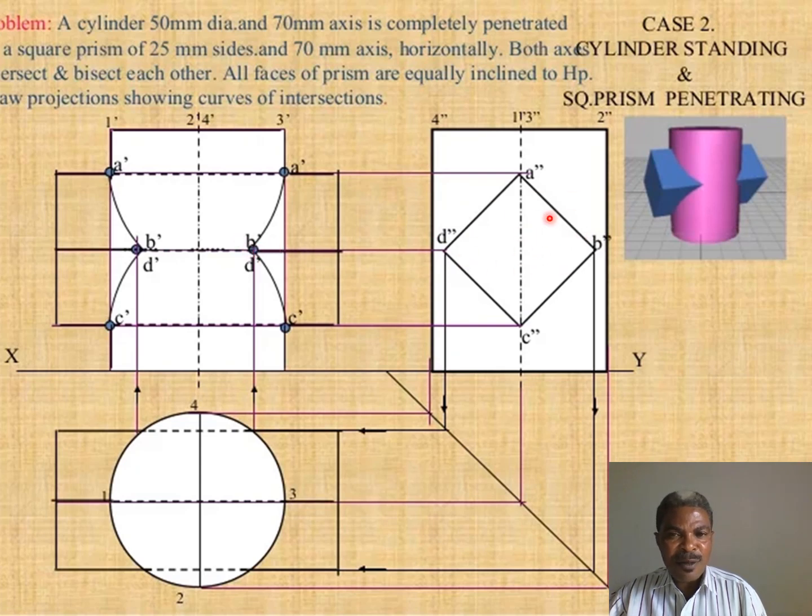They are starting from the end view with the two rods. One rod goes to the front view, another rod goes to the plan, then back to the front view. So at the front view is our interest to indicate how a curve of intersection or interpenetration is formed.